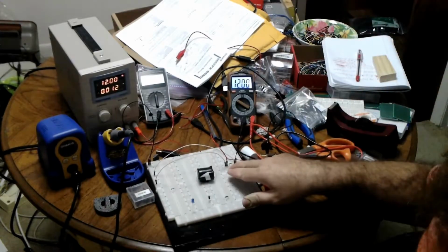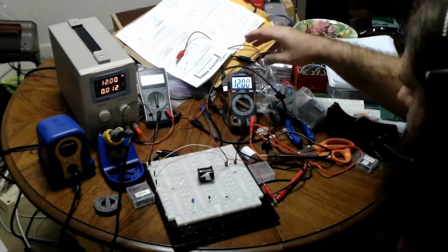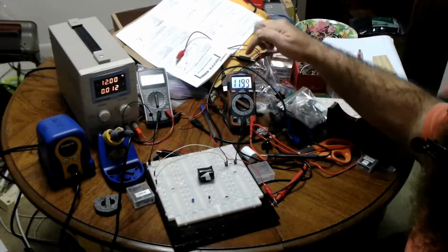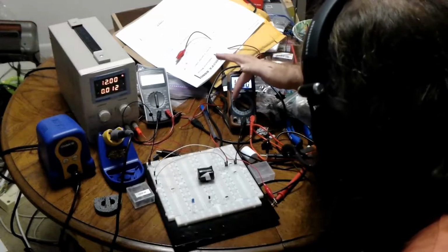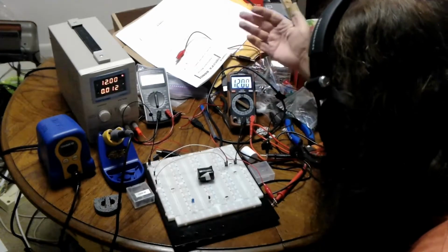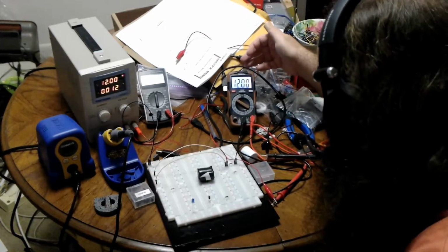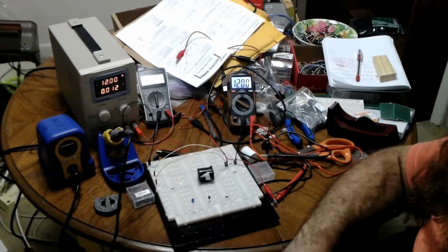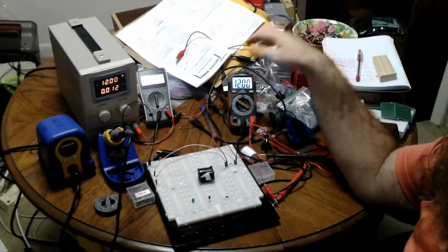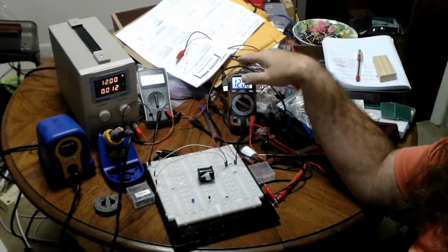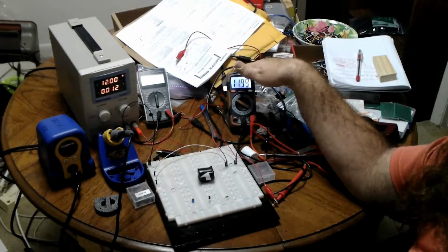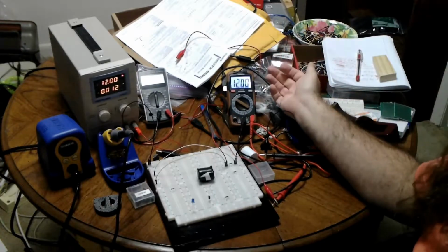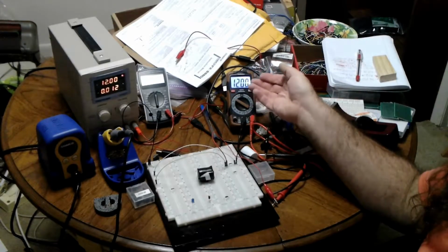But now, just measuring across the resistor, not changing anything, let's switch over to the AC voltage. Now, here's the fun part. The DC voltage has settings for 200 millivolts, 2000 millivolts, so 2 volts, 20 volts, 200 volts, and 600 volts, right? Lots of different options. The AC voltage starts at 200 and the other is 600. So clearly, this is not intended to be used for smaller bits of AC. And to be fair, you generally don't find smaller bits of AC. AC is wall power, so this is meant for measuring wall power.